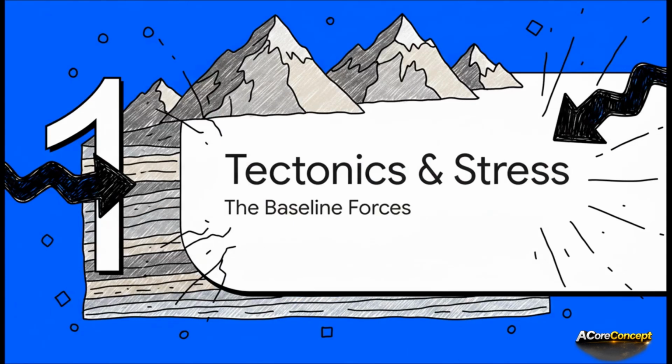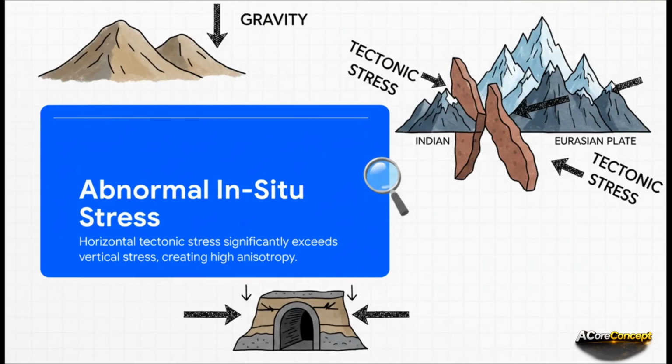Section 1. Tectonic drivers and stress fields. You really can't engineer a tunnel without first understanding the stress environment around it. Now, in older, more stable mountain ranges, the stress field is heavily dominated by gravity. That means the vertical stress, literally just the weight of the rock above you, is your primary engineering concern. But the Himalayas, they're a young, highly active orogen, about 55 million years old. The Indian and Eurasian plates are actually still colliding right now.